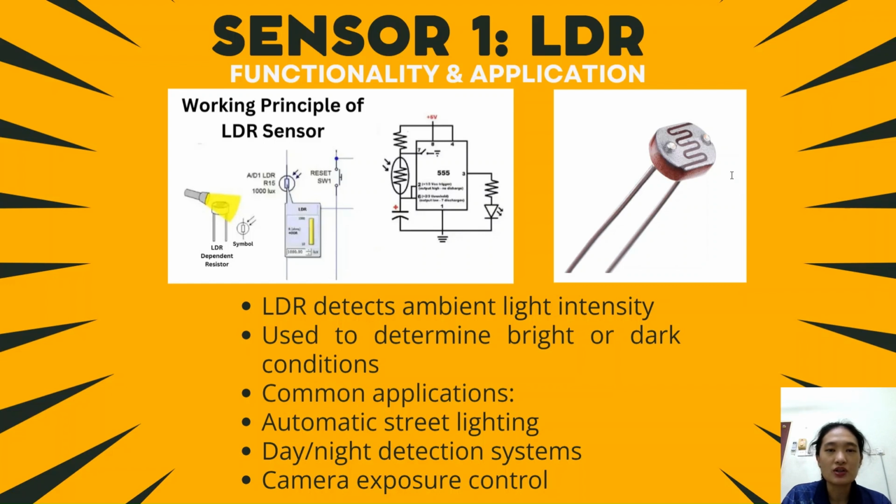This diagram shows the working principle of the LDR sensor. When the light intensity increases, the resistance of the LDR decreases, producing a higher voltage output. This analog voltage is used by the controller to determine the lighting condition.